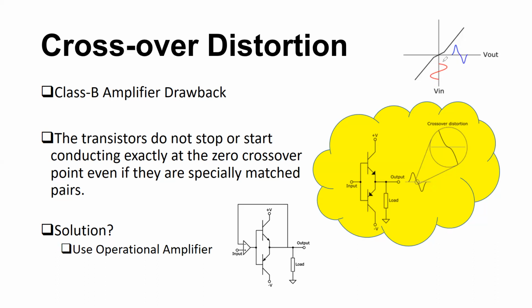Usually what happens is that when you are at zero input, obviously the output is zero. You see the red line starts from here and the blue line also starts from the middle. So no input, no output. And you are applying that input to the class B amplifier right here. For example, I am showing the output stage of the class B amplifier where you have used two complementary transistors. This is an NPN and this is a PNP transistor, right?